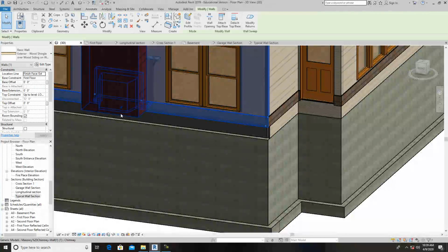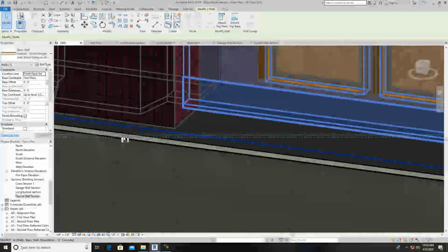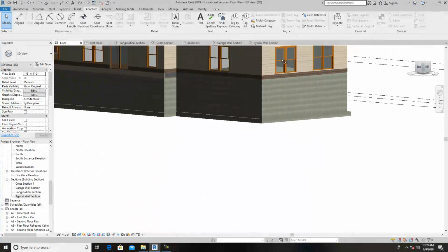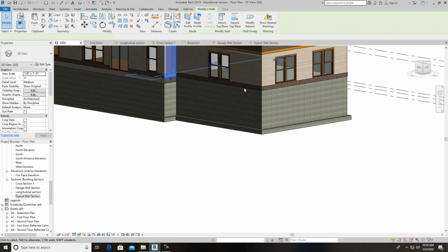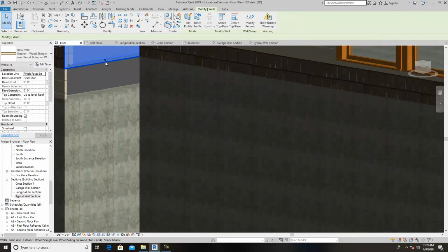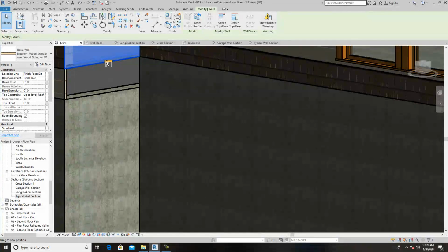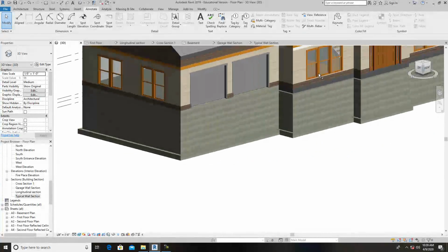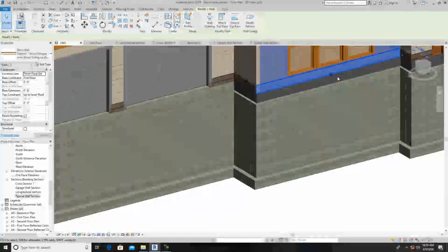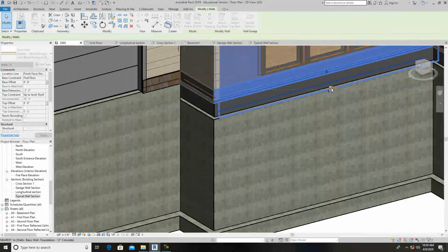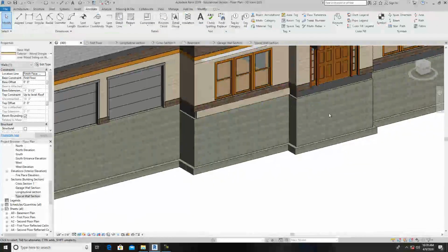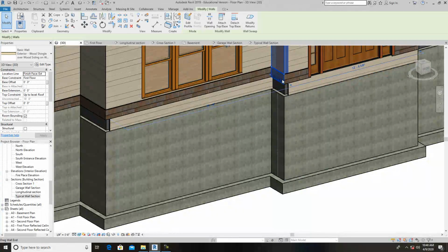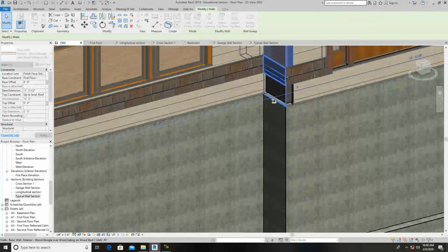You got to click on the wall, and you should see two of them. You just want to grab the outside one, bring that down. And the basement, or the garage, we already fixed that earlier in one of my videos. So now what I want to do is catch this one here. Perfect. Bring that down. We'll bring this one down to touch that wall.